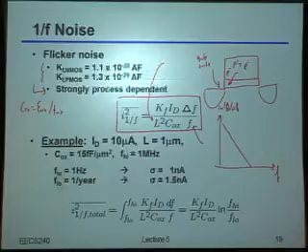So much like we said with Cox, if you make the transistor physically longer, then effectively you're increasing the total capacitance at that gate. And so for each electron that's jumping in and out, you're reducing its net effect on the threshold voltage, or equivalently the noise current density. By the way, another way of saying this is that with statistical things, if you average over a larger area or a larger number of events, the mean to variation ratio gets better. Okay, so that's one reason why increasing the channel length helps. What's the other reason that increasing that channel length reduces the drain current noise density?